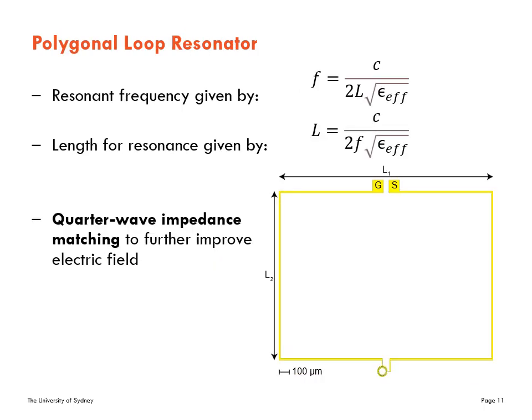I came up with a loop resonator design for the electrodes, which I have an example shown here. The ring's electrodes are located at the bottom of the loop. I used Sonnet software, which employs the method of moments to compute full-wave electromagnetic simulations of the design. The resonant circuit can be analyzed as a rectangular loop antenna, which is fed by a coplanar strip line.